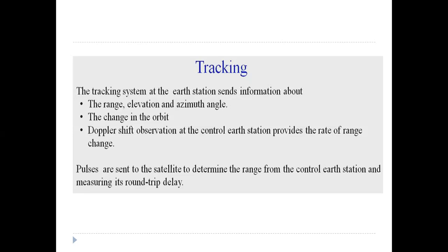A carrier generated on board the satellite is modulated with a series of sine waves at increasing frequency, usually harmonically related. The phase of the sine wave modulation components is compared at the Earth station and the number of wavelengths of each frequency is calculated. Ambiguities in the number are resolved by reference to lower frequencies and prior knowledge of the approximate range of the satellite.